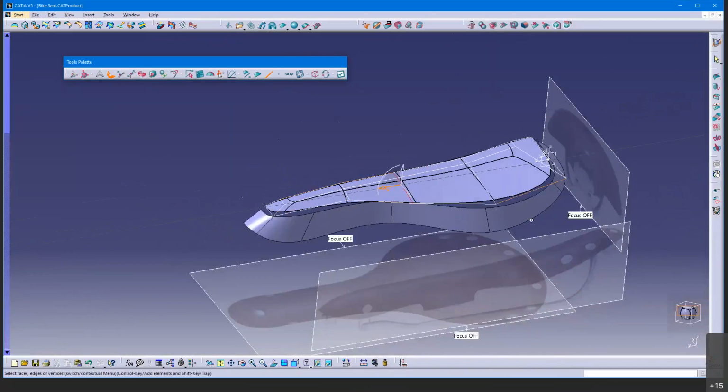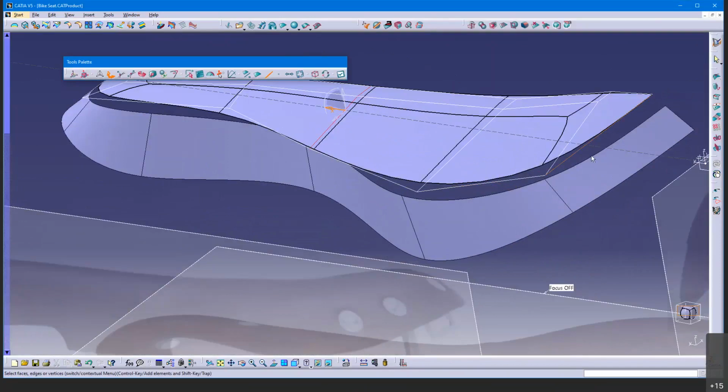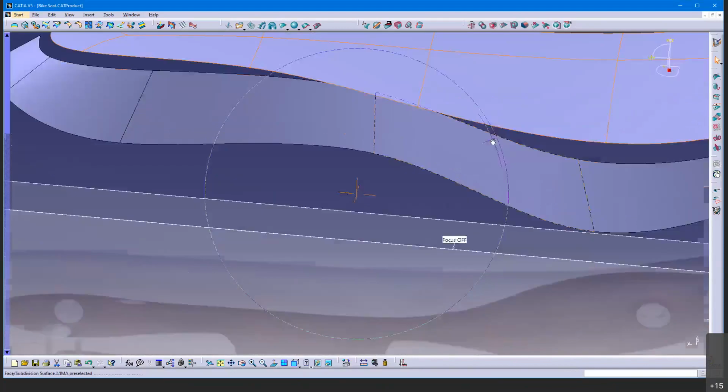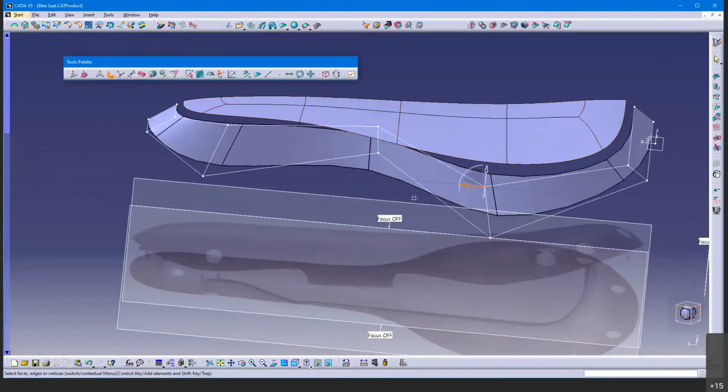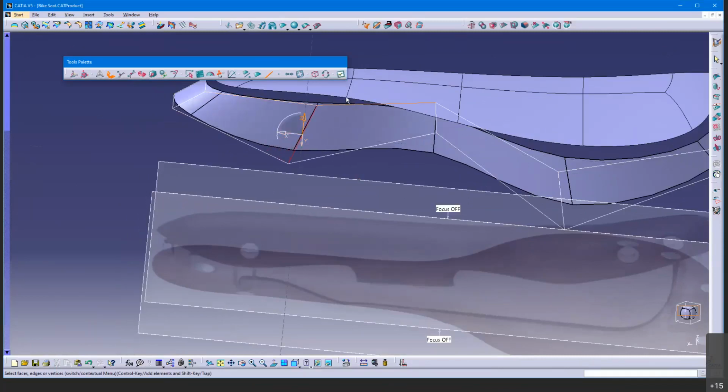So if I'm thinking back again to how my surfaces are going to merge. So I got these two merging. I've got these two merging, and I'm focusing in on these seam lines here. So far, not too bad. I probably need to move this one back this way and this one back that way, and then this one back that way. So I'm about as much as I can go on the top surface. So why don't I change to this surface? And so I can take now and take this one. So when I move that, now I'm moving this back closer to this surface.